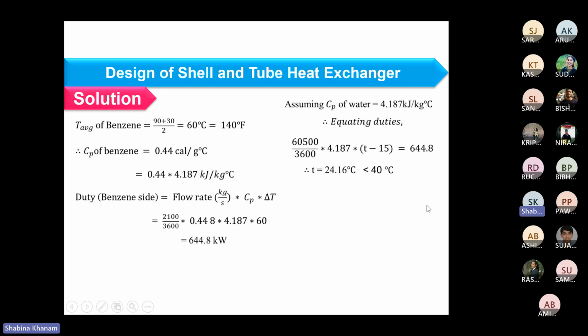So the solubility will decrease, which will precipitate the components available in the water, specifically the hardness material like calcium ion, magnesium ion, and so on. So solubility decreases beyond 40 degrees Celsius, and when you work on the system at more than 40 degrees Celsius, the scale formation will be significant, okay?